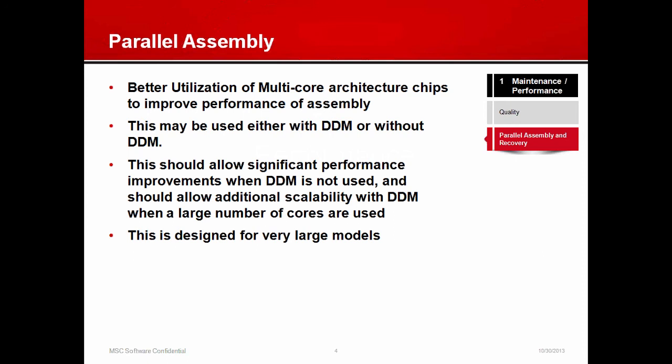So this complements the other types of parallelization that we have in Marc, which is either using the domain decomposition method or using the parallel solvers, whether it's the Pardiso solver or the MUMPS solver or even the multifrontal solver.